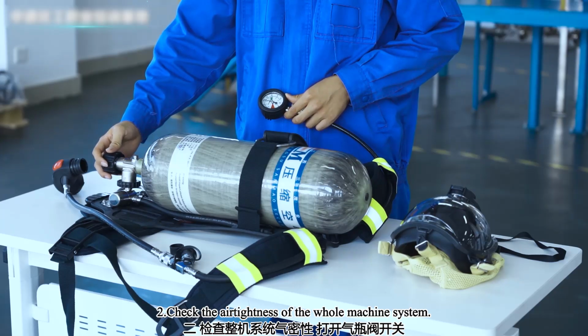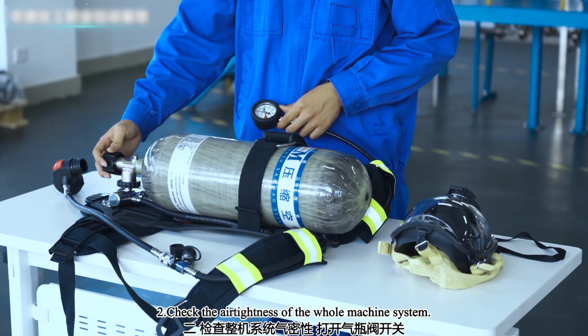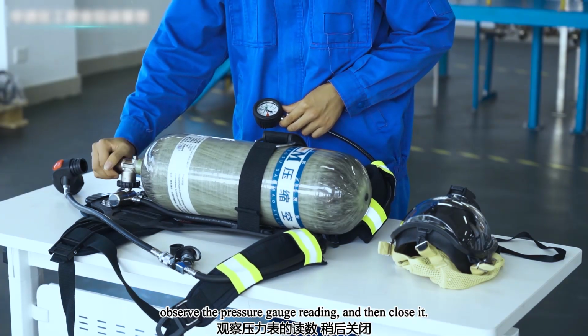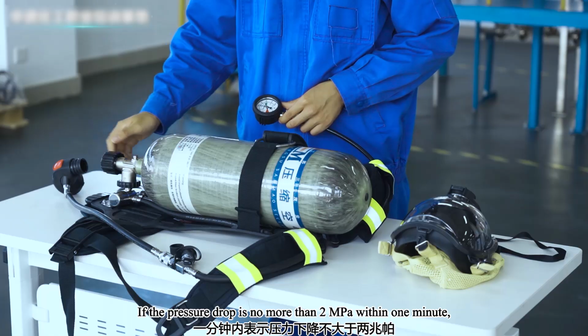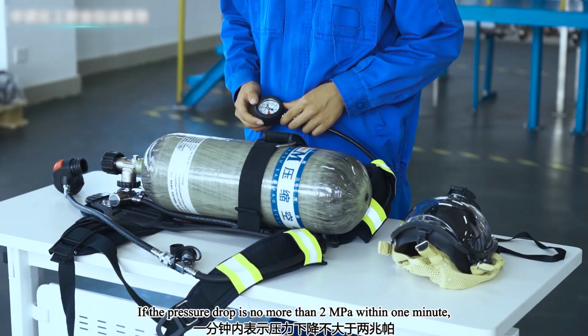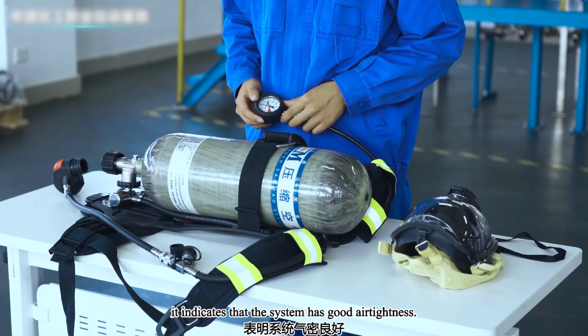Second, check the air tightness of the whole machine system. Open the cylinder valve switch. Observe the pressure gauge reading and then close it. If the pressure drop is no more than 2 megapascals within 1 minute, it indicates that the system has good air tightness.